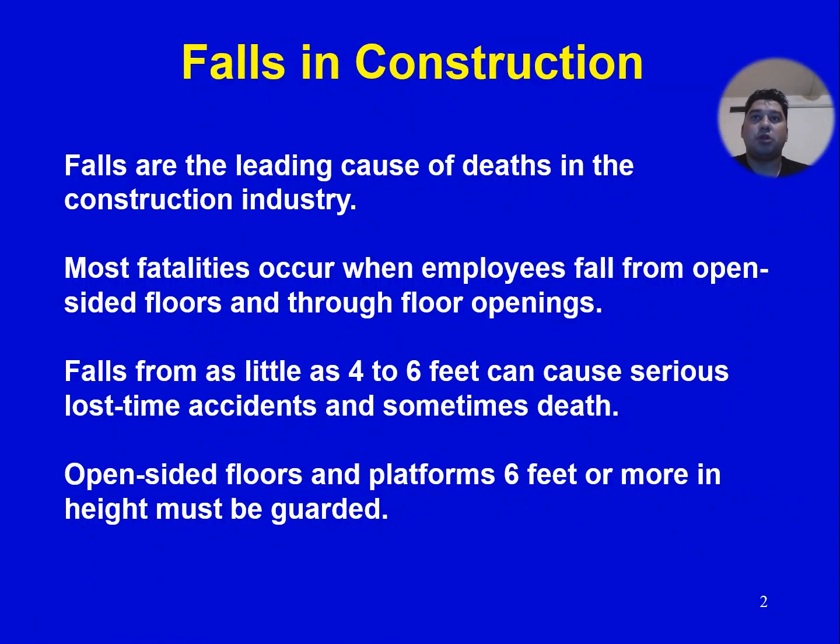Falls in construction. Falls are the leading cause of deaths in the construction industry. Most fatalities occur when employees fall from open-sided floors and through floor openings. Falls from as little as 4 to 6 feet can cause serious lost time accidents and sometimes death. Open-sided floors and platforms 6 feet or more in height must be guarded.